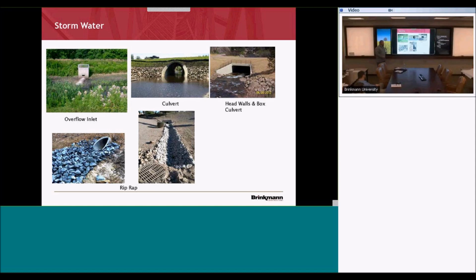So you need to make sure that when your sub comes in and says, hey, I can't get 10-inch riprap, I can only get 8-inch, is that all right? Well, it's not all right. Why? Because it's not plans and specs, and there's a good chance that it won't actually hold what it's supposed to do. So you got to make sure you get with your engineer of record.